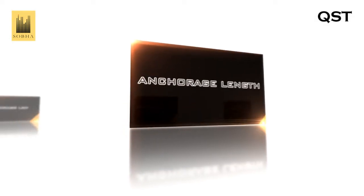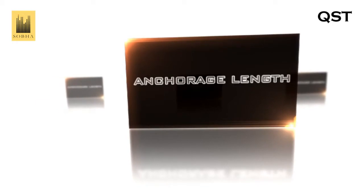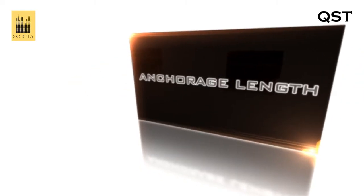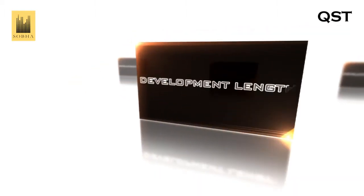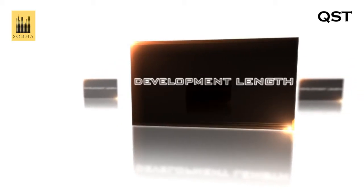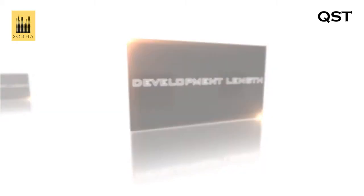Anchorage length. This is the additional length of steel of one structure required to be inserted in other at the junction. For example, main bars of beam in column at beam column junction. Development length. Development length can be defined as the length of the reinforcement bar embedded in concrete in order to develop full bond stress. These bond stresses prevent the reinforcement rod from getting pulled out of the concrete member because of tensile stresses when loaded.